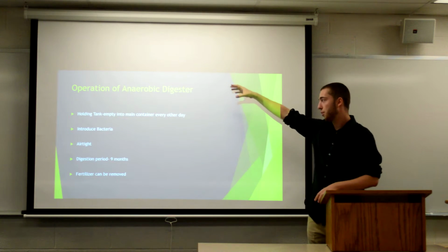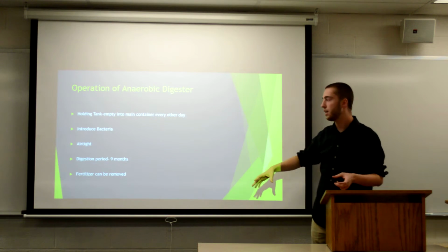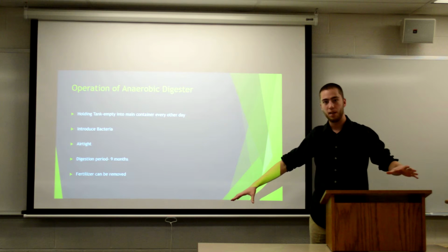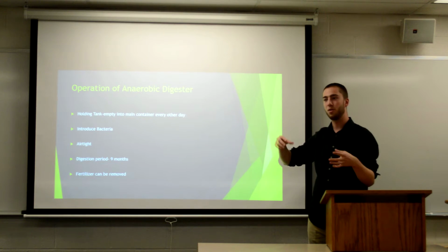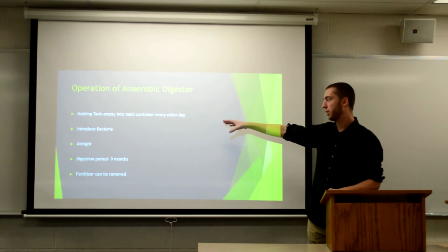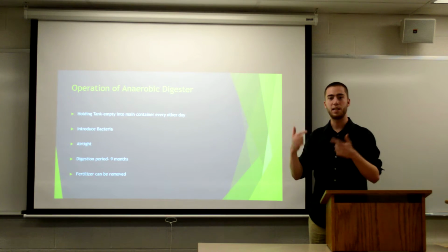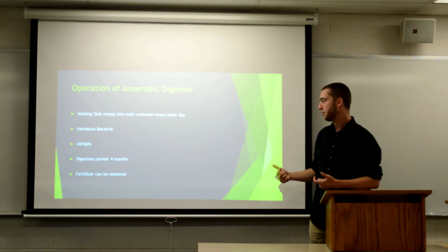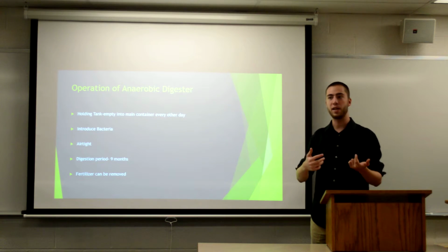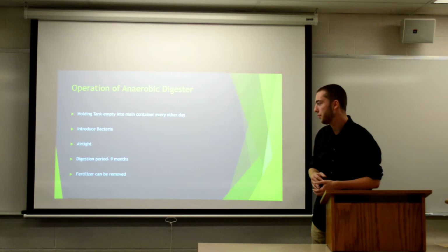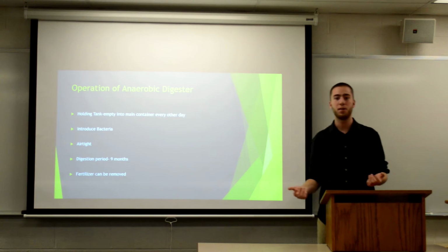Before you dump from the holding container into the main container, a bacteria tablet has to be introduced and then placed into the main container from the holding container. That bacteria is what facilitates the anaerobic digestion process. So it's very important to get the biogas and make sure that the process continues as it's supposed to. The digestion period is 9 months.